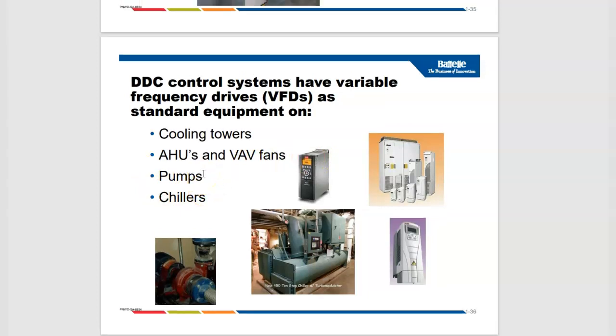You could increase the pump level to increase the chilled water, to open the pump so the chilled water goes and produces more chilled water, or you could increase the speed of the compressors, perhaps by using a frequency drive. This is the purpose of the DDC, digital direct control.